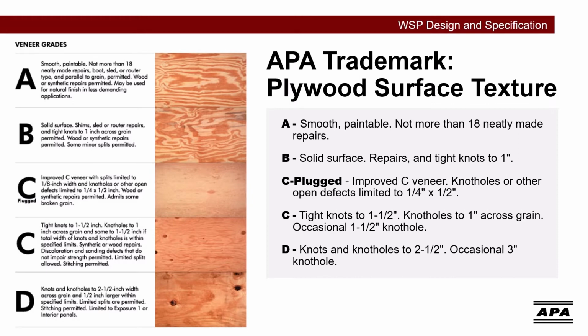Plywood panels are often referred to by their face grades. Take CD rated sheathing panels, for example, often referred to as CDX. CD refers to the grade of the face and back veneers of the plywood panel, respectively.